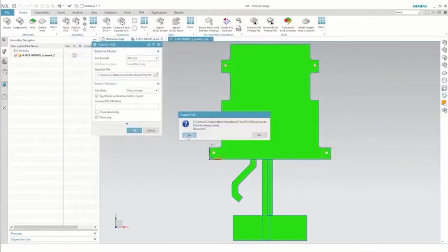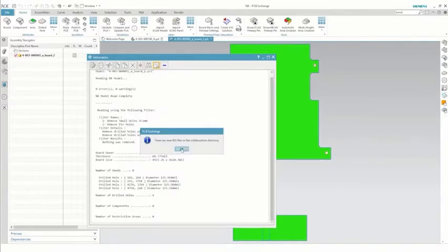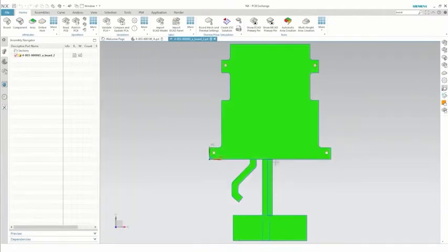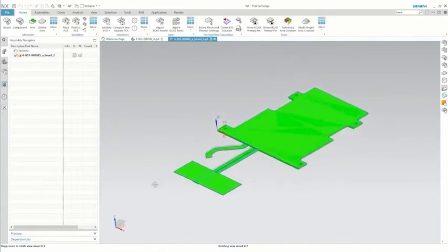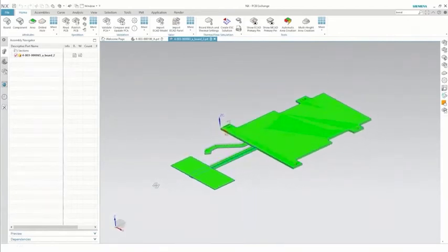Hit OK, and we go ahead and publish this, and then we'll be able to go over to the PCB and import this directly in and start making modifications for some of the overlapping flex areas, defining the flex regions, and working with the bends. So you would think the mechanical engineer would be able to do a lot of the bend stuff, but mechanical tools don't have any of the intelligence built in that we need and that we'll talk about here in the PCB tool.